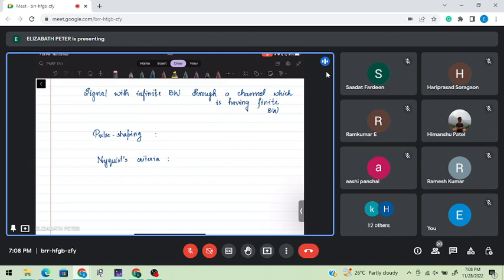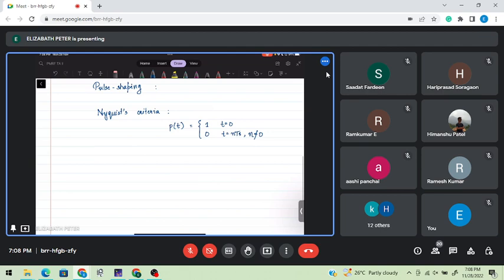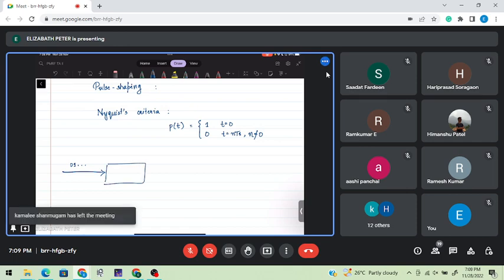The signal p(t) should have the property that it is 1 at t equal to 0, and 0 at all other t's. A stream of zeros and ones comes in at the transmitter, and once you assign a shape, through what is called a pulse shaping filter,